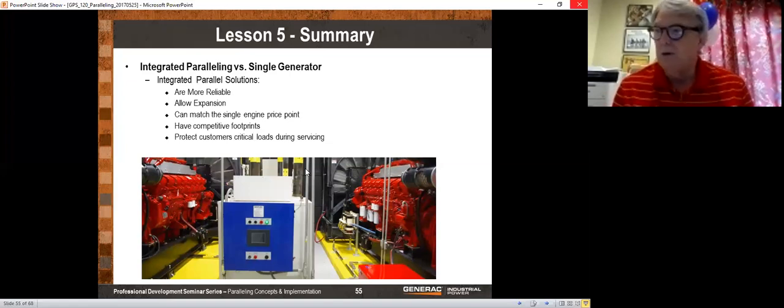You need to make sure that where you plug this thing in, we typically use cam locks, make sure that they're all color coded, and make sure that we get the right phase relationship and so on. One of the problems with that is that most people who do this, you have an automatic transfer switch, and when that sees a power outage, it's going to start the generator, and then the generator runs. When the power comes back, it stops the generator, and all that's automatic. Well, when you come in with a portable, now it's not going to be all automatic because you don't have that same automatic 2-wire start.